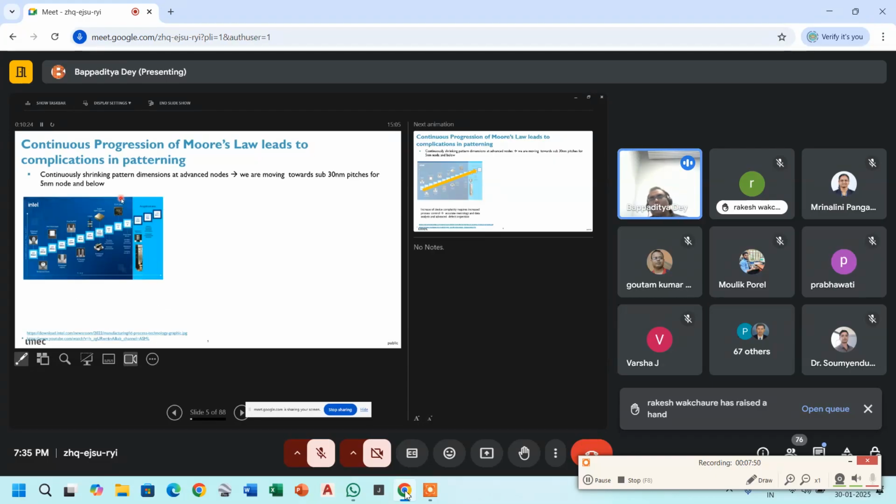So we know the technology roadmap we are heading towards right now. Again, don't go into my definition of the technology node; that is quite critical, it is just something I have to refer to. We are standing in a domain going towards 2 nanometer and beyond technology nodes. The technology node definition started from the transistor, which we all know, right? A transistor has a gate length, or channel, which is mainly responsible for carrying the current. When the technology roadmap started, the definition followed how much we could squeeze the gate length so that the number of transistors doubles, following Moore's law, like every 2.5 years the number of transistors in a chip mainly doubles. Right now, we cannot follow the trend because we reached the physical limit a few years back. But still, we are trying to make progress to keep Moore's law surviving, right?